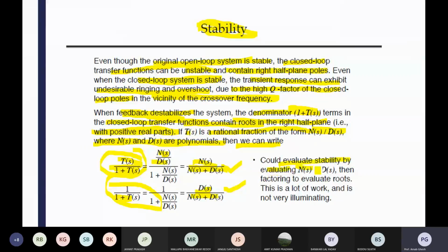The Nyquist stability theorem is a generalized result, so you are able to use it. A special case of the Nyquist stability theorem is the phase margin test, which tests using your phase margin. How much is the range of your phase margin? Is it positive or negative? If it is positive, what is that value? If it is negative, how much is the value? Is it a stable, positive phase margin or an unstable, negative phase margin? From there you can understand.